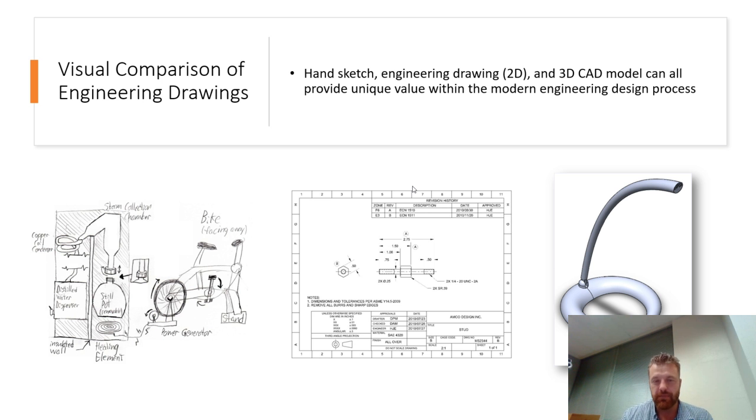In the middle, we have what you would call a plot or a print. It's reflective of engineering design 20 to 30 years ago, and still useful today if you're going to manufacture anything by hand in a machine shop, or if you're trying to support inspection or quality assurance workflows. You're going to see these types of drawings all the time. Their format is standardized by either ASME or ISO, depending on what standard you're working with. Around the outside, you have these zones, kind of like a spreadsheet, numerical and alphabetical identifiers that divide the drawing space up into little grids, and you can point to them.